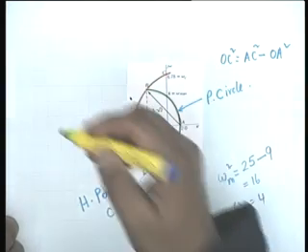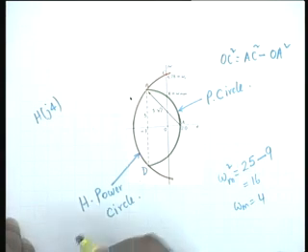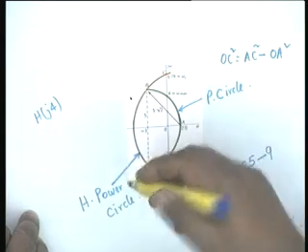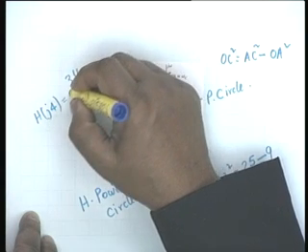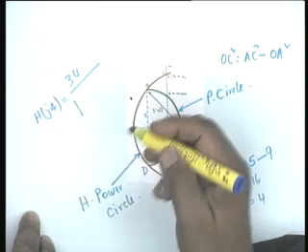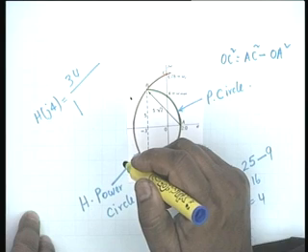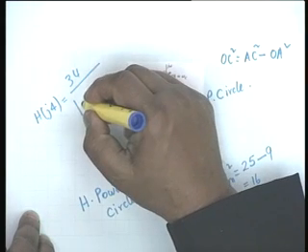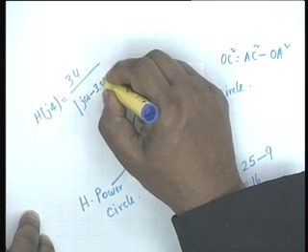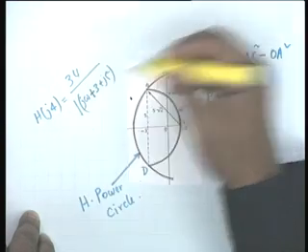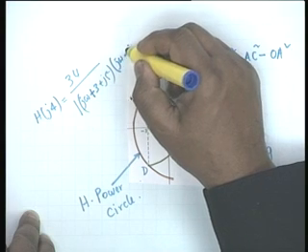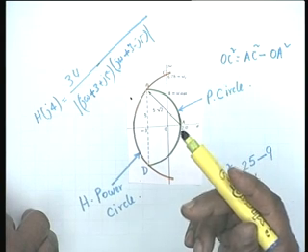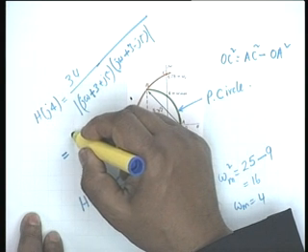Then to find out the maximum H of j4, well, there are various things you can find out in terms of zeta, or you can find out directly from the equation, that is it is 34 divided by magnitude of j omega minus 3 plus j5, j omega plus 3 plus j5, j omega plus 3 minus j5, okay, magnitude of this, and substitute omega equal to 4, because that is the maximum, and the final result is 34 by 30.